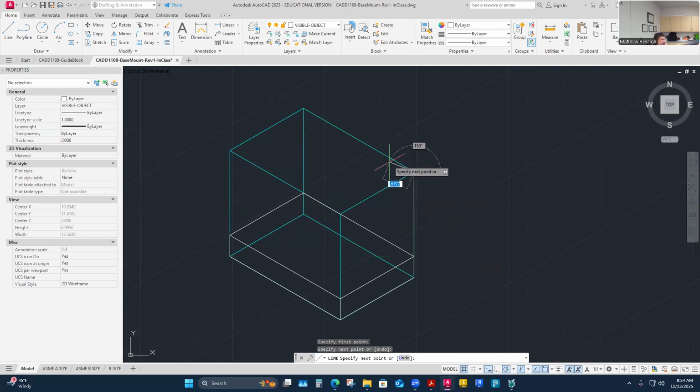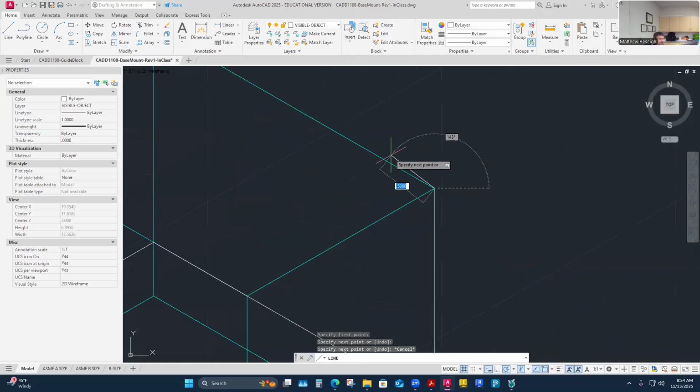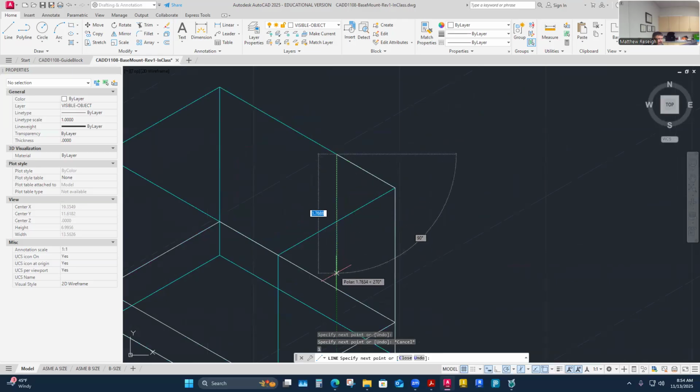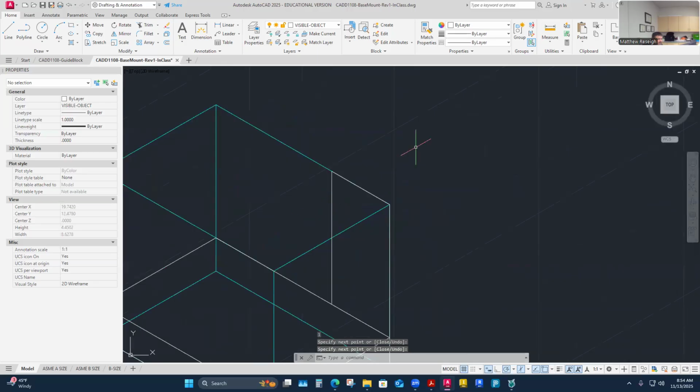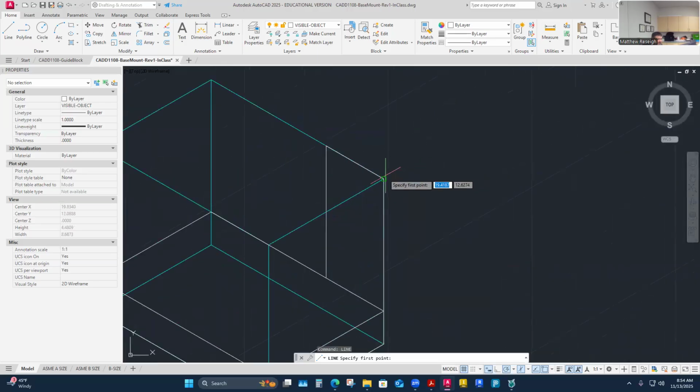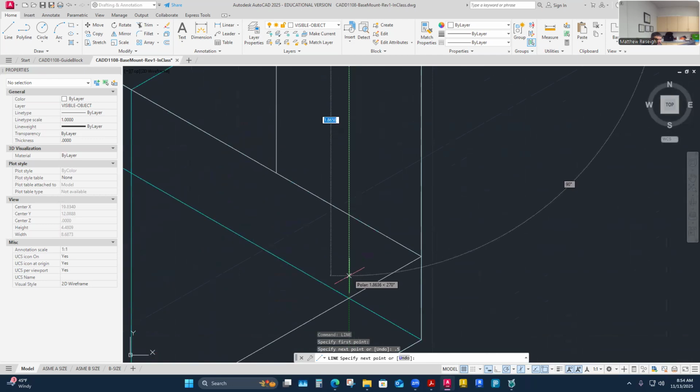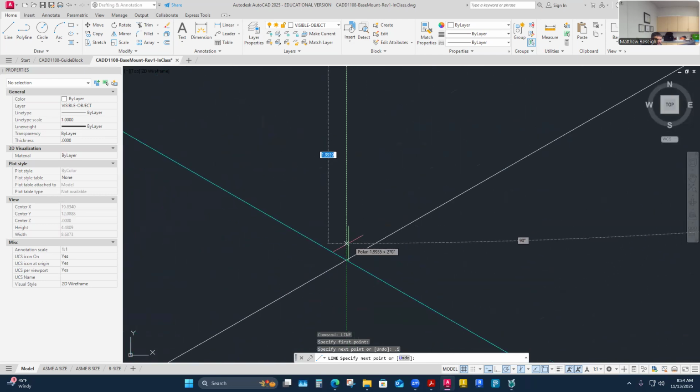And this thing, I know it's round on top, but it's only a radius of 1/2 inch, so it's 1 inch wide here. I'm going to make sure I'm on my projection. 1 inch. And this would go down to where it would meet the back edge like that. It's a 1/2 inch thick, so I can show that right here, 1/2 inch. And it comes down to where it meets that little top plate. You've got to zoom in, make sure you're snapping to the right things. Looks like there's some alignment there too, that's fine.